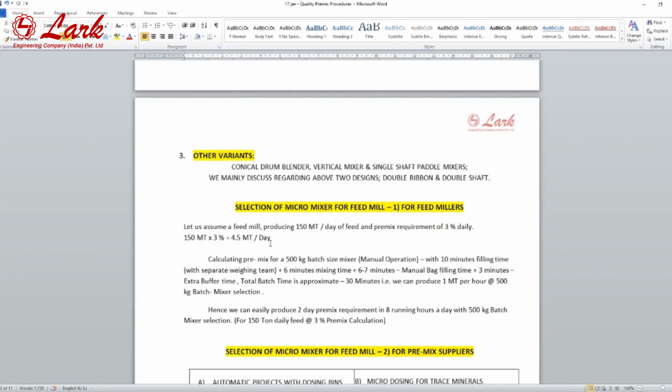For someone having a 10 ton per hour broiler feed mill, the motor of the hammer mill is around 150 HP, and the RPM of the hammer mill is around 2800 RPM, because in broilers we require grinding at a 3 mm or 2.8 mm screen with a particle size less than 900 microns, for more than 80% of the average.